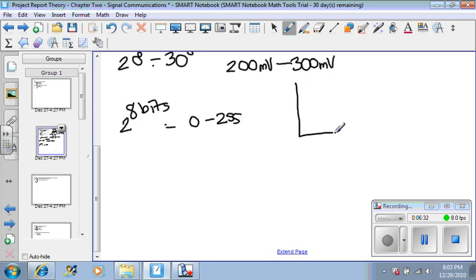So I have another scale that I draw with relation to the temperature sensor. It says as the temperature sensor goes between 0 and 5 volts, I go between 0 and 255, which can be read by the microcontroller. But it appears that the temperature sensor is only using a small fraction of the whole 5 volts.